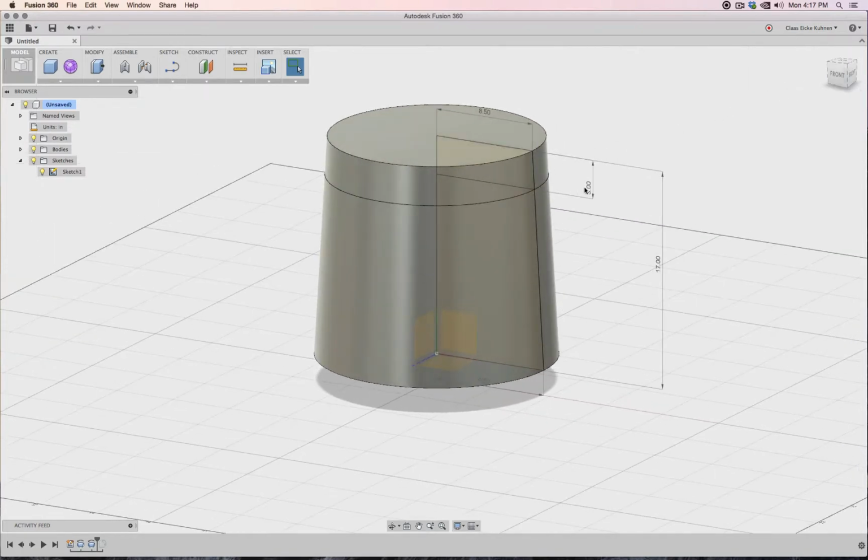Now again, the awesomeness of the sketch engine, 4 inches, zip. We see we changed the sketch, that changed the first revolve, that changed the second revolve. How awesome is that? Now I moved my cursor far to the right. Now this fillet bugs out. It says it's red. And that makes sense because we first built this whole piece, then we selected this edge and said round it.